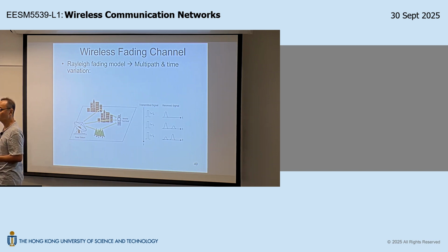Is that okay? In other words, the basic physics behind this inverse square law is that the power or energy gets spread over a bigger and bigger surface area, or the transmit energy gets diluted over a bigger and bigger surface area. There is no ohmic loss. So this is different from coaxial cable, where the loss is due to ohmic loss.